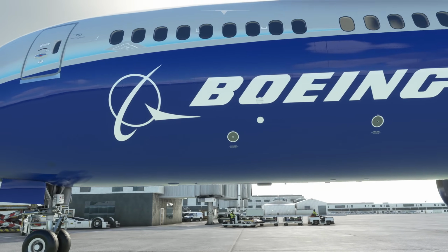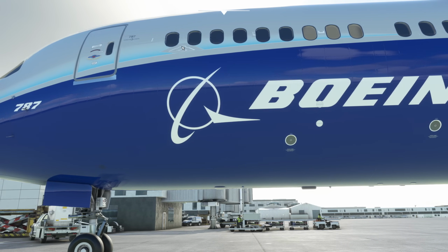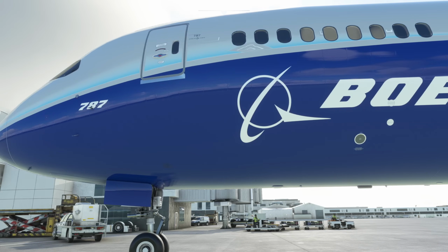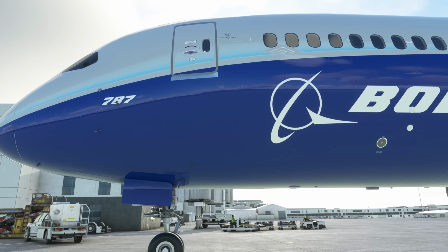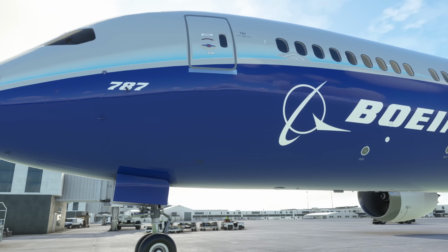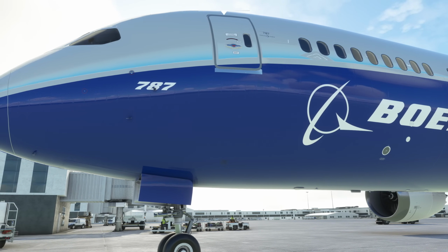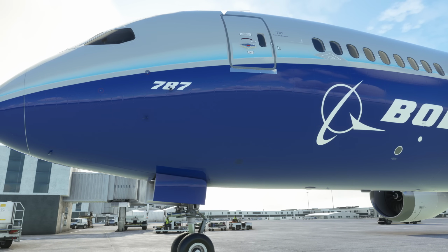As we move further forwards, you can see, by the way, big windows. They slightly change your perception of the size of the aircraft. They make it look a bit smaller, I think, than it is, because they are really quite big, really fantastic. So they run all along the side, obviously, and they can occasionally have a little rubber seal around the outside that has a performance penalty if that's missing. So you do look for any obvious damage on those, and there's our door one left.